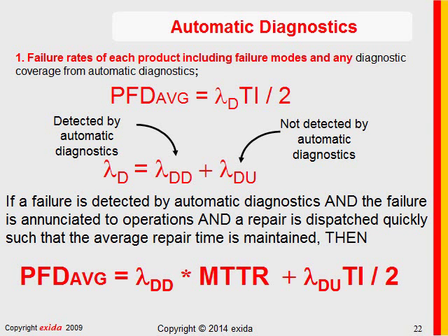Well, the logic solver programmer or the system designer can choose to either make that a trip, or the logic solver designer, in most cases in the process industries, annunciates that failure so the repair team can go out and fix or replace the transmitter rapidly.